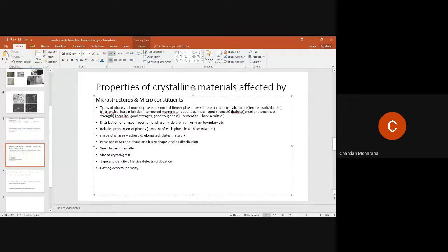But do you people remember what is the difference between pearlite and bainite? Both are the same mixture of the same thing. Let me see, anybody remember that? Sir, grain size is slightly smaller in bainite. Okay, fine. Yes. In case of bainite, it is a very fine microstructure, but pearlite is somewhat coarser, with bigger size grains. Okay, very good. That is one part.